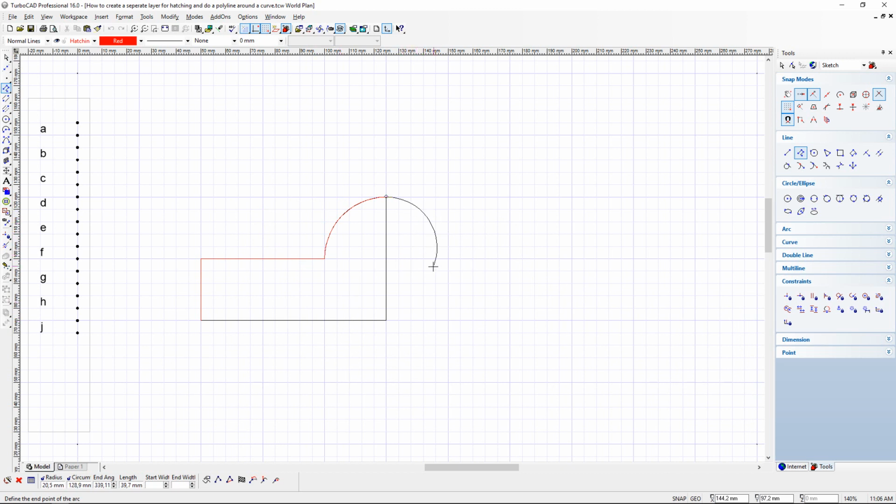So now to change this arc, I want to go back to these buttons at the bottom, and I'm going to select the straight line polyline option, and then it returns the polyline to a straight line. Snap to the corner, and then I go back to where I started from. Now I have this line. I call it the poodle on the leash. So I have it, and what do I do with it now?